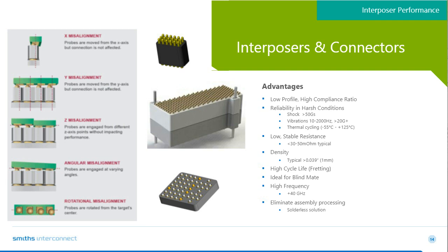It prevents any FOD from interacting with the interposer because it is an installed state now after the washing and the cleaning of the boards. It allows for the system to be mated or demated for rework and testing freely without risk of damage to solder joints during the unmating processes. It can save on installation costs by not actually having to be soldered to the boards. Not to mention now you're only using one interposer or connector instead of two mating halves.